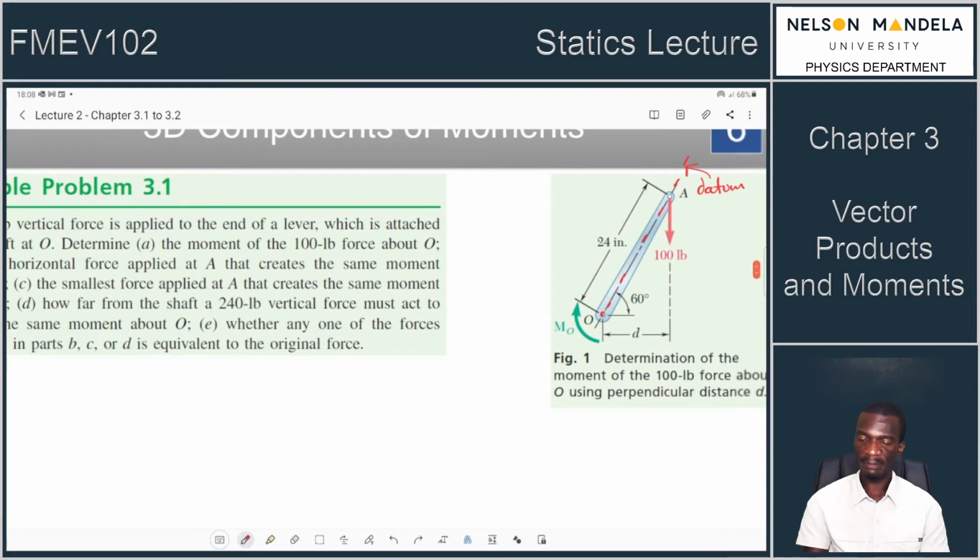So for the free body diagram, we've got our reference point. We've got our reference frame, x and y, so that's the first important part. Then we need dimensions, so let's draw the object. In this case, we cannot just draw a point. We're now talking rigid bodies. On that rigid body, while it has its own weight somewhere, we have a force given at point A, acting in the vertical downward direction. Let's just call it F is equal to 100 pounds in the minus J direction.